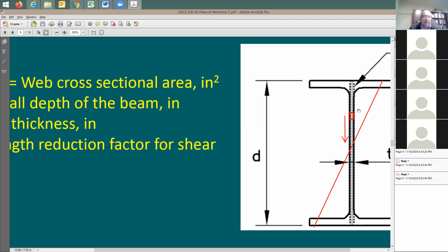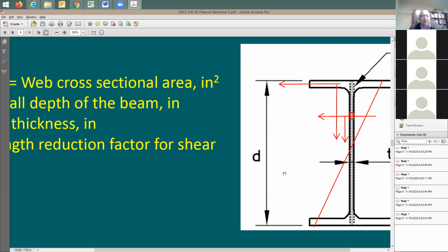Now we need to take the force developing here. Here's the force, right? Let's say this is going to be the tension side, just to make it simpler for you. Take this tension force multiplied by this distance to give you the moment due to the force right here. Compare it with this cross-section area, which is really big, multiplied by this distance from here to there. Which one's larger? Number one, this is now getting closer to the center of the beam. Number two, this cross-section area at this height is going to be very small compared to this cross-section area at this height.